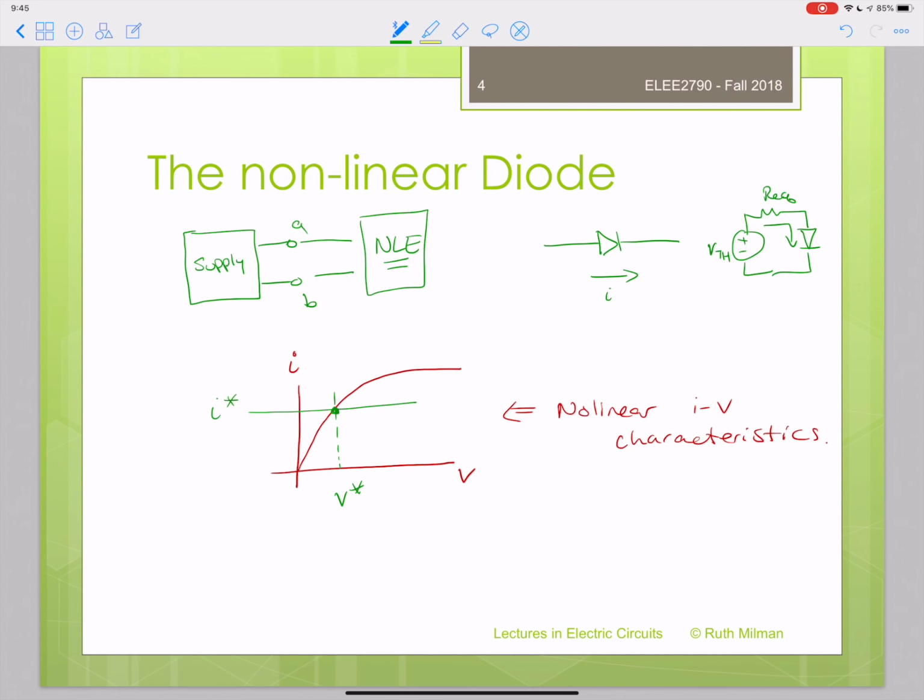And so you can completely understand what the voltage is going to be when a particular current goes through the diode, and everything is described entirely by this current voltage graph. Sometimes it's a graph, sometimes it's an equation, but this will explain what happens within the diode itself.